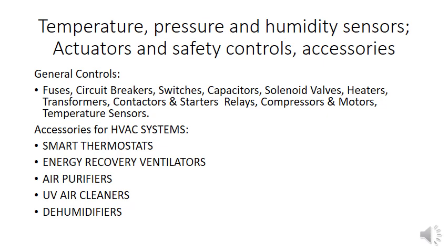Then energy recovery ventilators. Sometimes the cold air is much more in some zone of the central air conditioning units, so that cold air, or maybe in winter the heated air, can be taken to the ventilators and circulated through the air handling units. Also, air purifiers are part of the modern accessories of a heating ventilation system, because they purify air by decontaminating it.